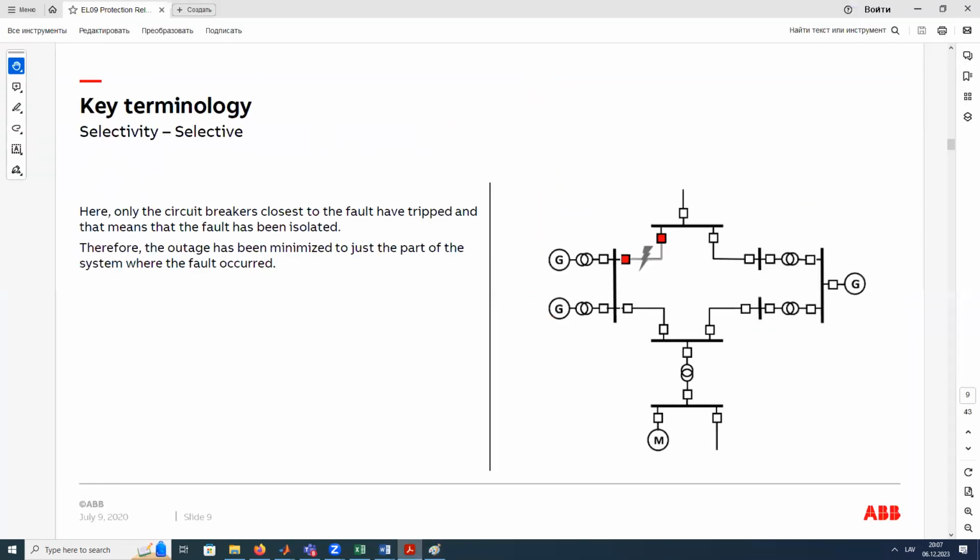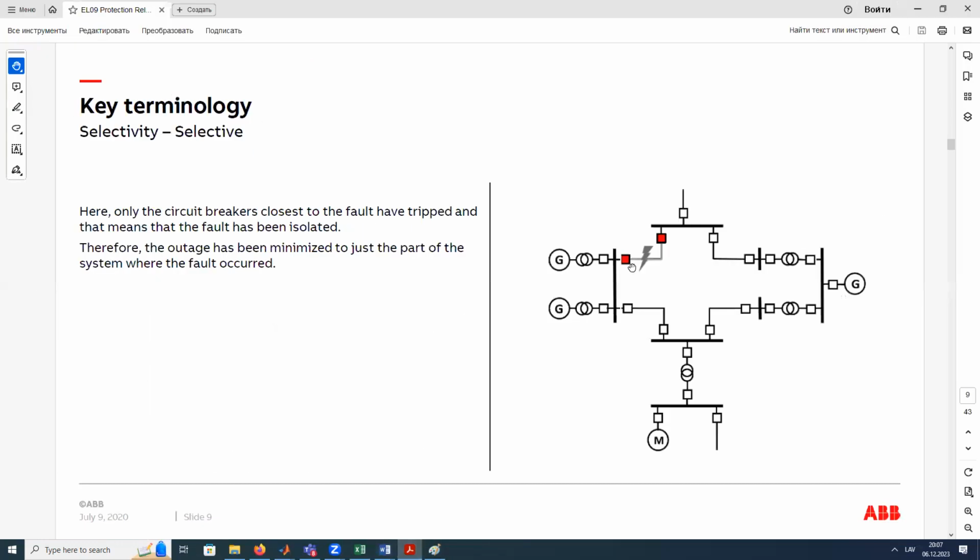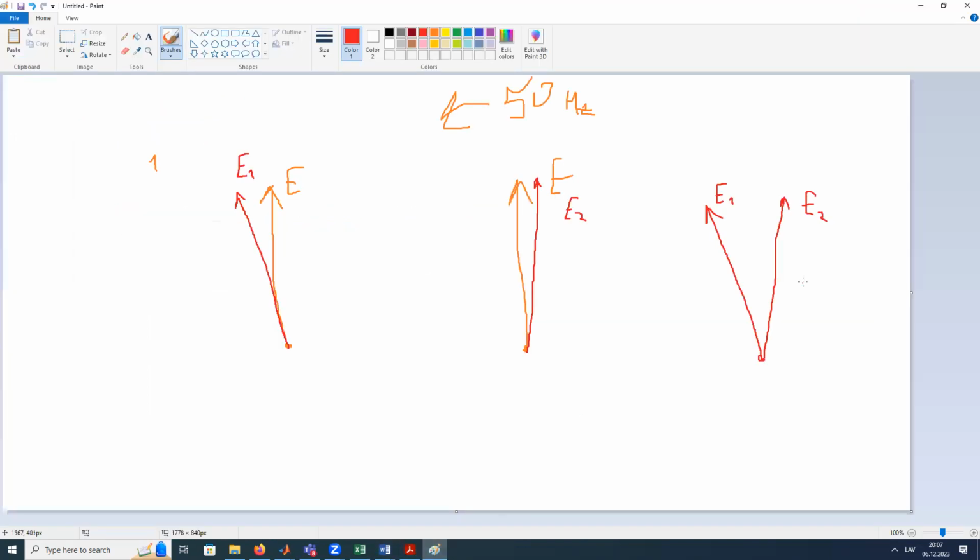And if we run a recloser here, at once, closing the breaker for one part, the breaker for the second part, and every line from here at once connecting here and here, what is going on? Because we have an angle here, they are not synchronous, and we get this resulting electromotive force. As a result, a high current value that is dangerous. That's why we can't connect it back if we have this angle. We can only connect it back when they are synchronous.